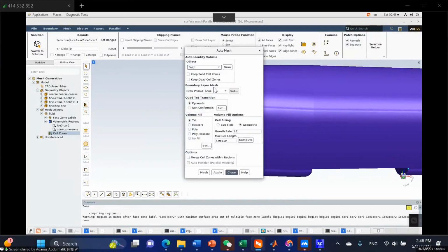So this boundary layer is an option. There is a criteria. To use some computational models, you must have a certain number of boundary layer mesh that can create a certain y plus value. I don't know, maybe I'm going too deep here.